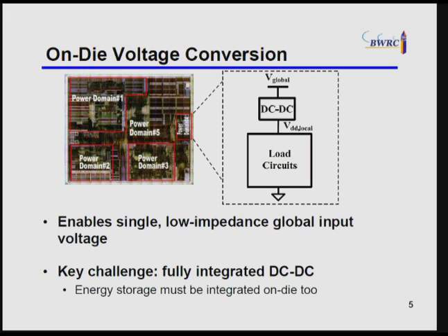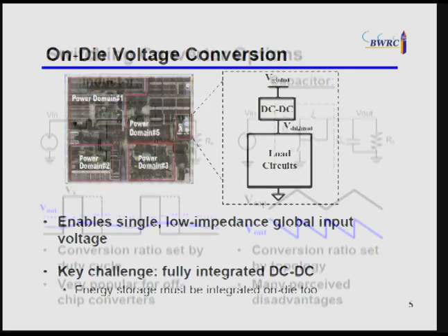Of course, the key challenge in doing this is, how the heck do you build this fully integrated DC to DC converter? I don't think there are too many people from the power electronics field here, but because there's often a misconception in that area, when I say fully integrated, I really mean fully integrated. Energy storage, transistors, everything has to be on the chip. Because any time you start playing other games, you very quickly end up paying substantial area, cost, or efficiency penalties, okay? That's why, as you heard earlier from Don, there's a lot of interest now in integrated magnetics to get that key energy storage element onto the chip as well.